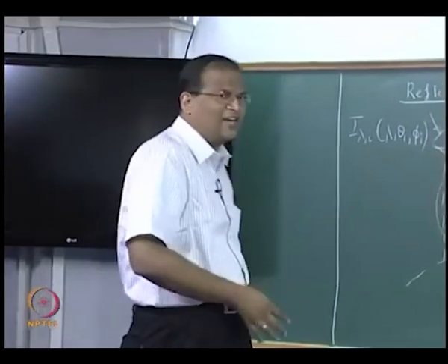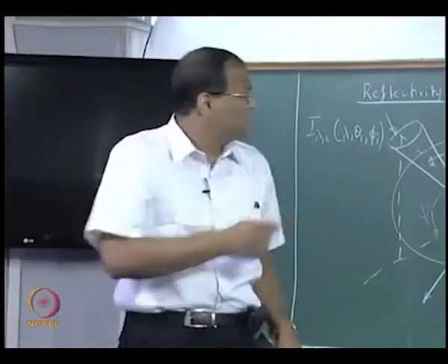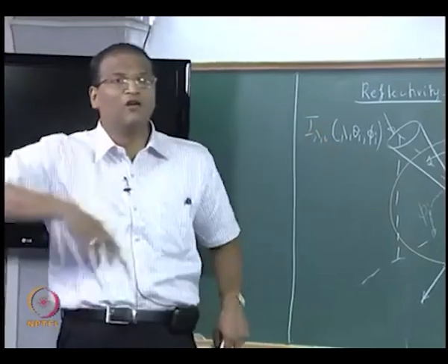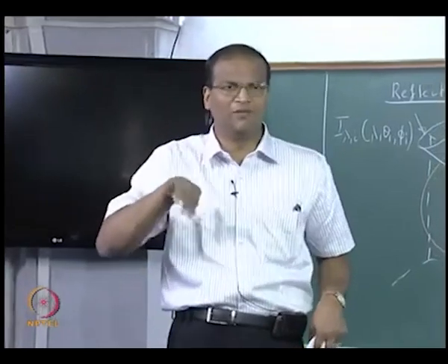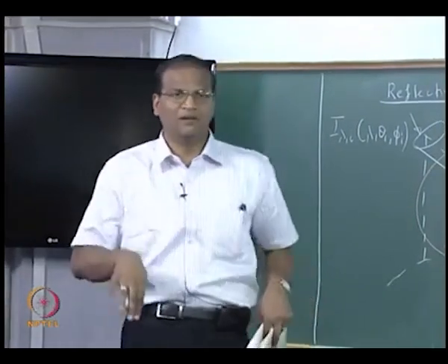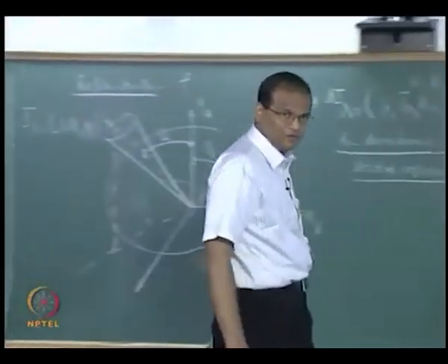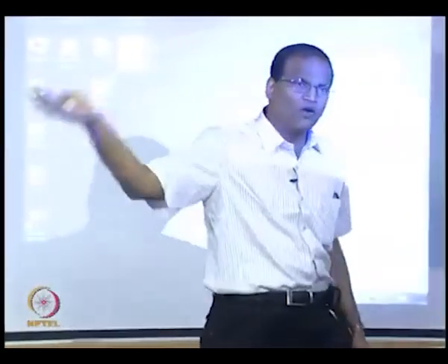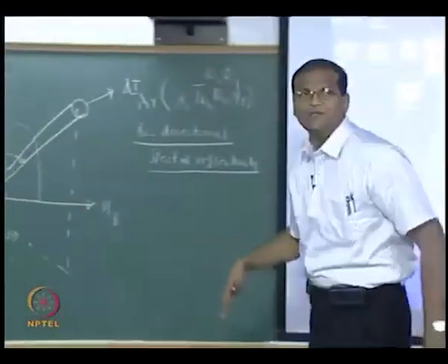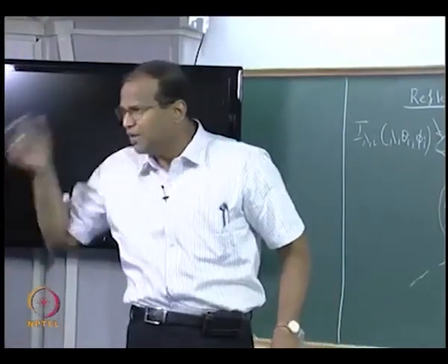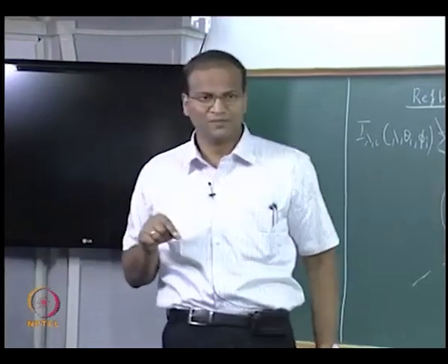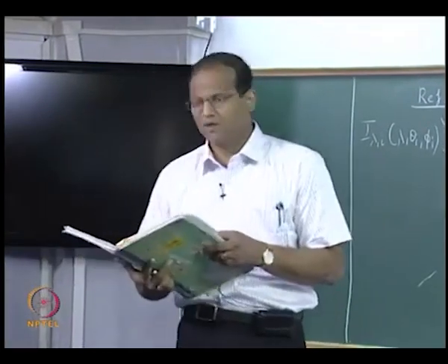No, I lambda I is a finite radiation which is coming in. But since we are not considering whatever is going out in the full hemisphere, only in a particular direction, I expect that to be a very small quantity as opposed to I lambda I. Therefore I call it dI lambda r. Correct? Because it can go equally in all the directions, unless it is a very specular surface or something. Consistent with my understanding, if it is a diffuse surface, a surface which can reflect in all the directions, what is coming out in a particular direction will be much smaller compared to this. Therefore I call it dI. Is that clear to everybody?